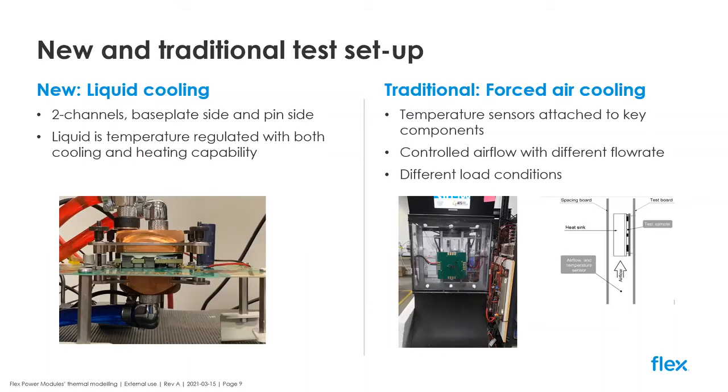Instead of controlling air speed, it controls temperature on 2 channels, one for base plate and one for pin temperature. The reference sensors are attached to the base plate and the joint between the output pin and the test board. It's possible to program an independent base plate and pin temperature. A third regulator finds out the maximum power that can be reached without overheating the converter. The thermal blocks used are for standard desktop CPUs, and you might find attachments for those blocks on future test boards from Flex. But let's move to looking at the output data from those systems.